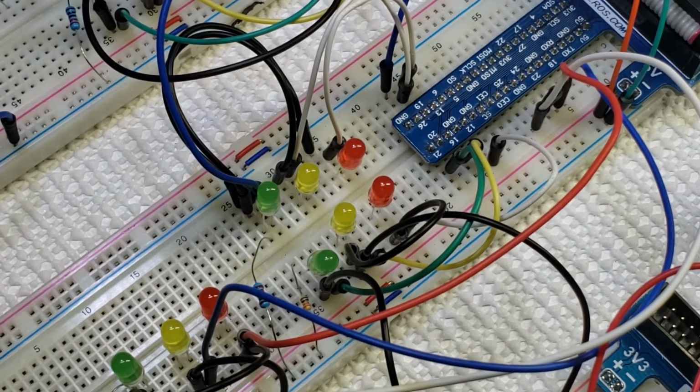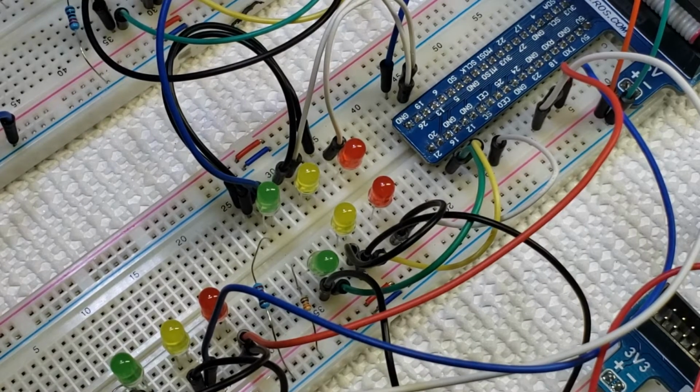So we need to indicate that on our schematic. All GPIO numbers go to the anode side of our LED, and then we have the negative side, or cathode side, going to our resistor, going to our negative side for our voltage. As you guys have learned, when we apply voltage output to that pin, then the LEDs will turn on. What we don't have is a specific schematic for the electrical circuit that we're working with right now, and that's what homework number 5 is.